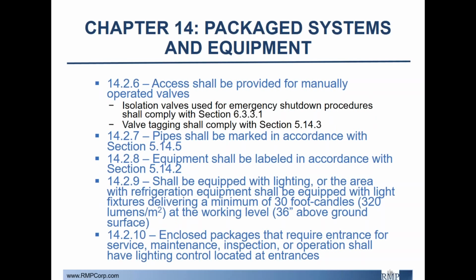Access to package systems shall be provided for manually operated valves. Isolation valves used for emergency shutdown procedures shall comply with Section 6.3.3.1, which states that manually operated valves that are inaccessible from floor level shall be operable from portable platforms, fixed platforms, ladders, or chain operated. Pipes shall be marked in accordance with Section 5.14.5, which discusses the requirements for pipe markings. One very important requirement is that they should all say "AMMONIA" in big capital letters on the side of them. The next section discusses equipment that shall be labeled in accordance with the same chapter, and